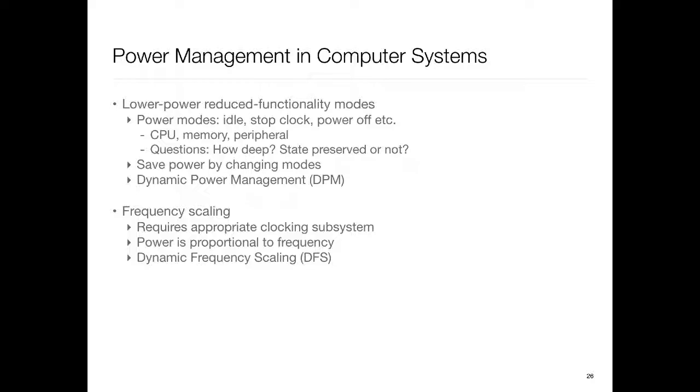Okay, and as I mentioned, voltage also has a role here. So what is the role of the voltage? Voltage dictates the maximum frequency you can operate at. Because if you increase the voltage, ignoring second order effects on reliability, then I can operate the processor faster. So F max goes up. You can really think of this as a joint problem. As I operate the processor at a lower frequency, I can also, if my power supply is so designed, lower the voltage so that F max equals whatever frequency I need.